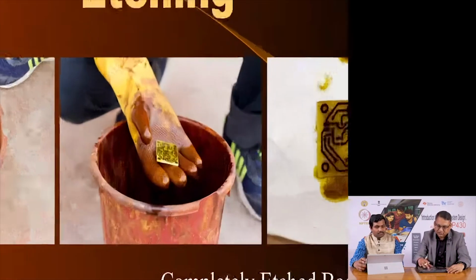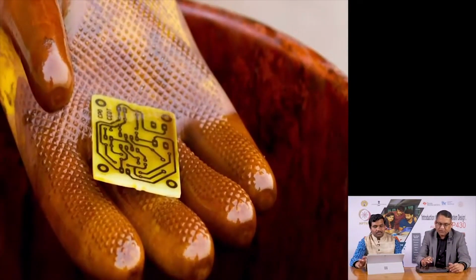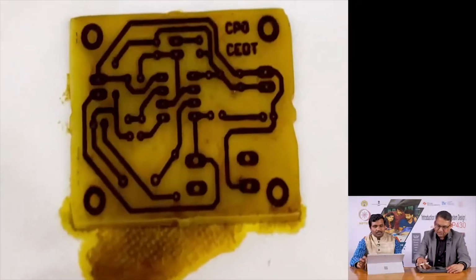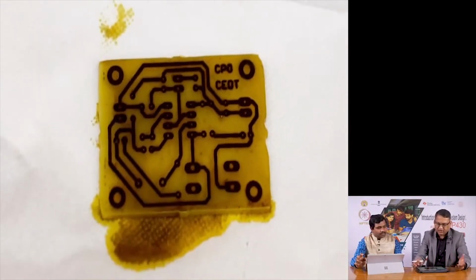And this is what you see once you take the PCB out of the solution: the copper is gone, only black tracks are left, and the substrate of the PCB, which is the fiberglass material. Here is what it looks like, and it has just been placed on a tissue paper, so that additional ferric chloride is absorbed.